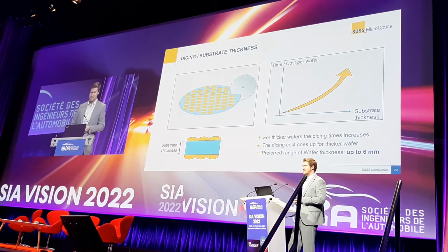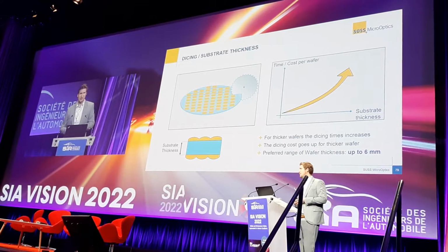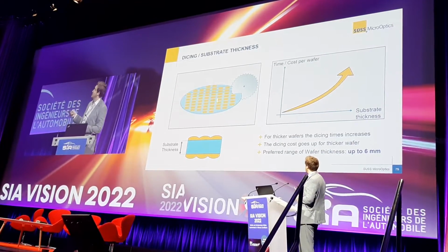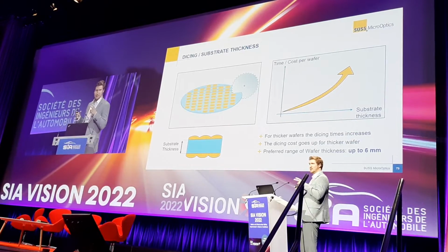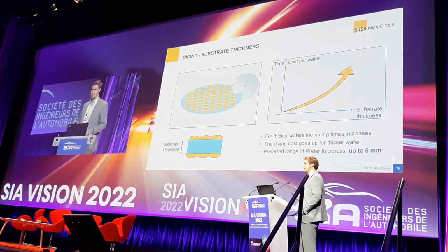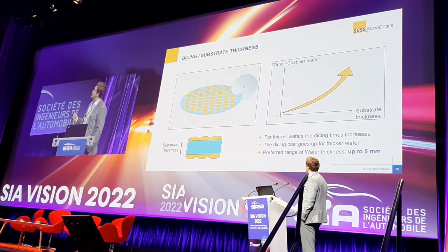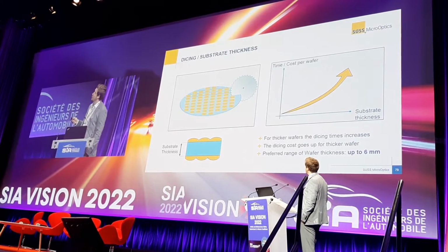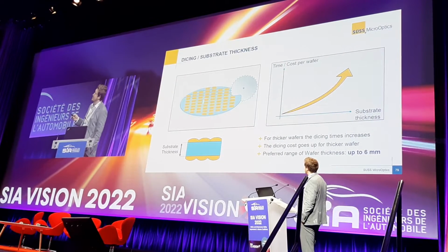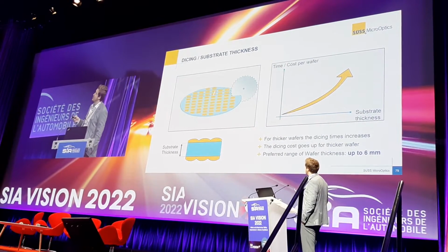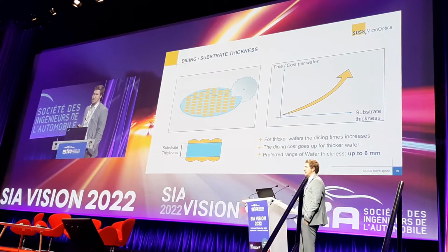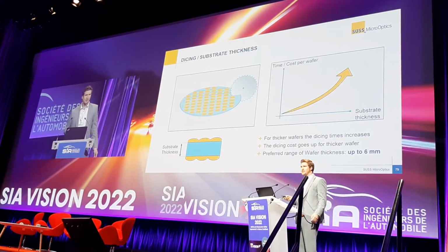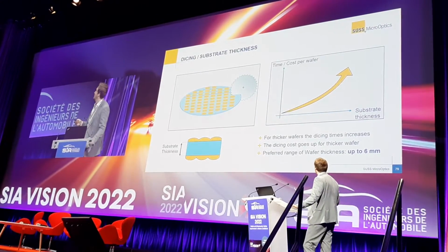So having finished this, the dicing process is coming. You can see here the wafer, which is around 200 millimeter at the moment. This is also what we're currently changing. And there are the MLAs on there, and then it's getting diced and separated, so we have the single chip after the dicing. And there, this is a design rule, I would say.